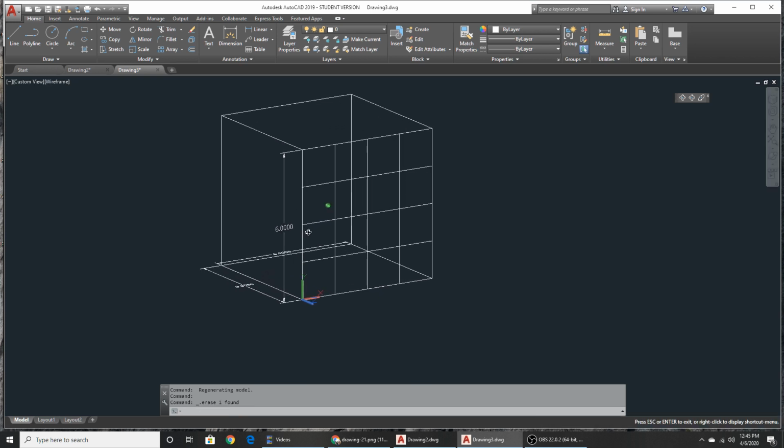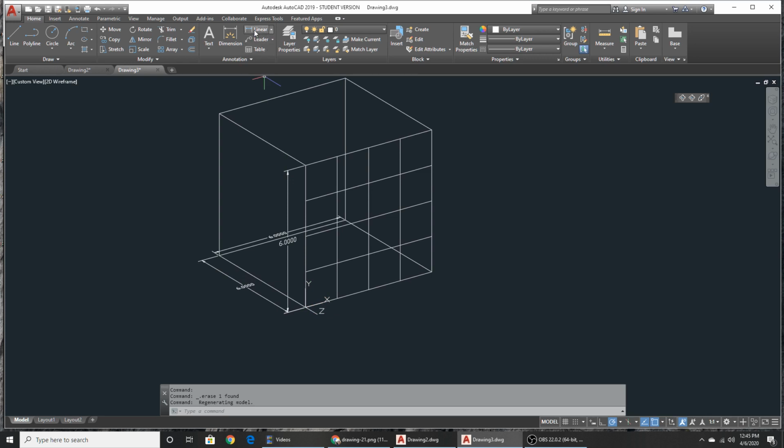I'm going to try this again, but I'm going to use the actual linear dimension here and not let the computer try to do any of the guesswork for me. And hey, look, I can pull that down. Now there's a 1.5. We already know, because I measured it earlier, that that's a 1.5. Let's just check this here, make sure it's a 1.5. Yeah, okay.